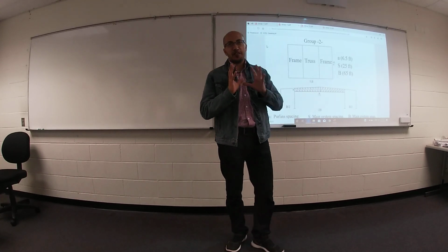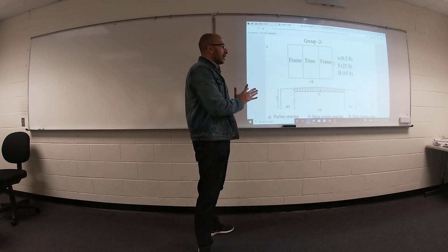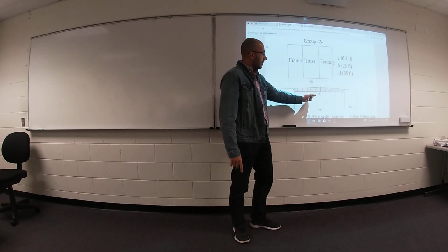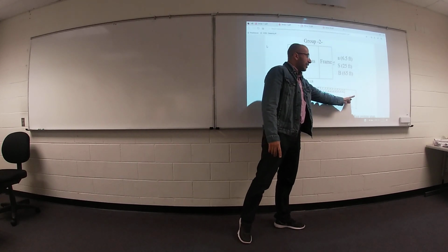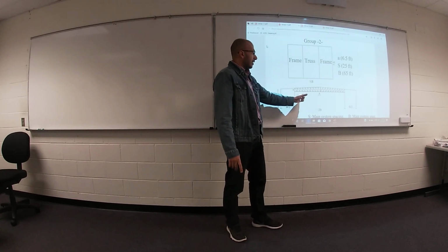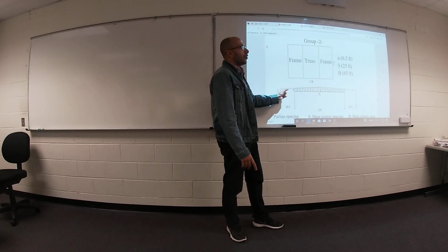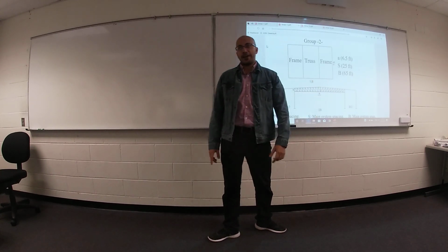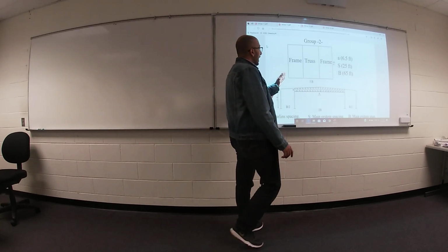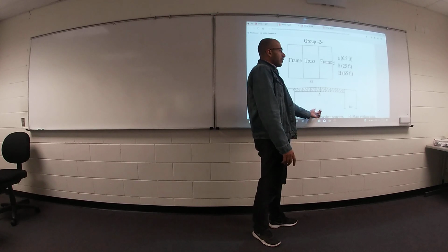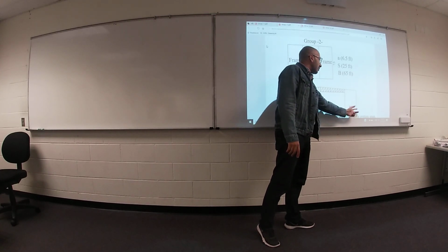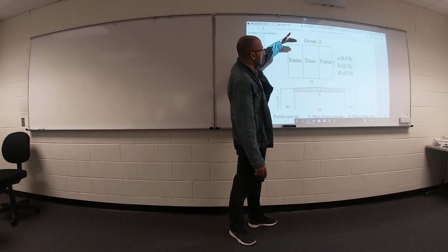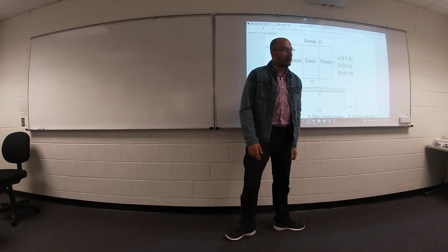Your main system is a little bit different today for this group. Your main system is a combination of two structures in one structure: truss and frame at the same time. This column serves for the truss and for the frame also. So your main system consists of truss and frame at the same time. Your total span is 3B. We have here 2B, half B, and half B, so the total span is 3B. It will be spaced for 7 spacings, each spacing equal to 25 feet.